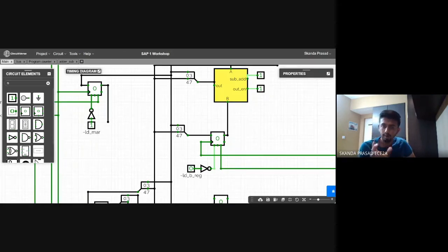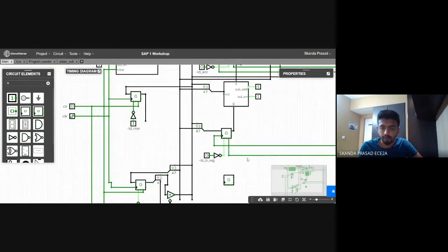It's just a flip-flop being converted into a register, and based on what the logic is, it should go to the bus or it should go to the adder-subtractor. Depending on that, we choose the tri-state or not. If you're dealing with a bus, if from any circuit element it has to go to the bus, it has to go through this tri-state because we don't want contention anywhere. The tri-state will enable, only then it will go onto the bus, we dump it to the bus. So that's the only logic there. So don't get too tense when you see all the tri-state registers everywhere.